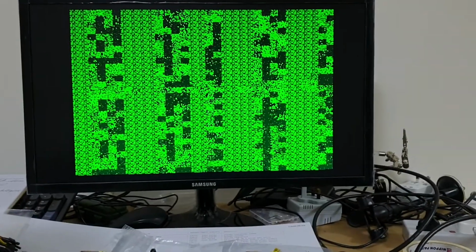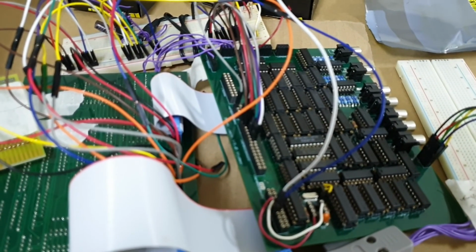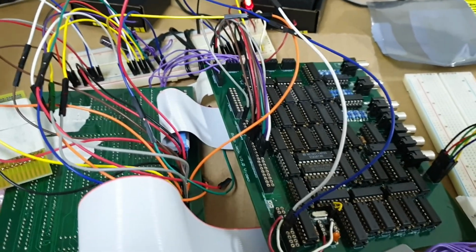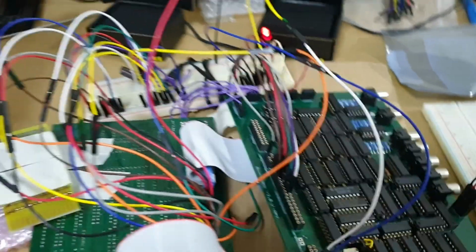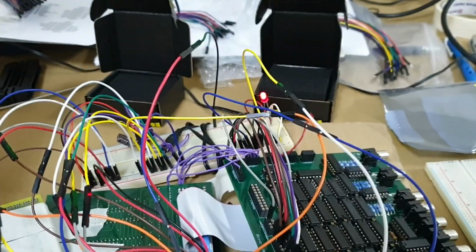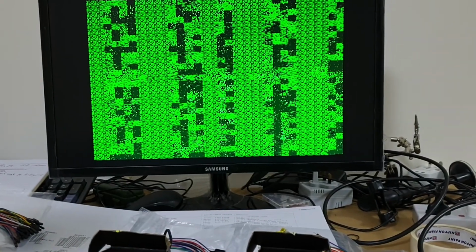But yeah, cool, very nice. So yeah, tidy up this board with the interconnects. Remove all of the debug wiring, which is asserting all of the memory addresses and data buses, and then start connecting up to Commodore 64 user port and getting that to work.